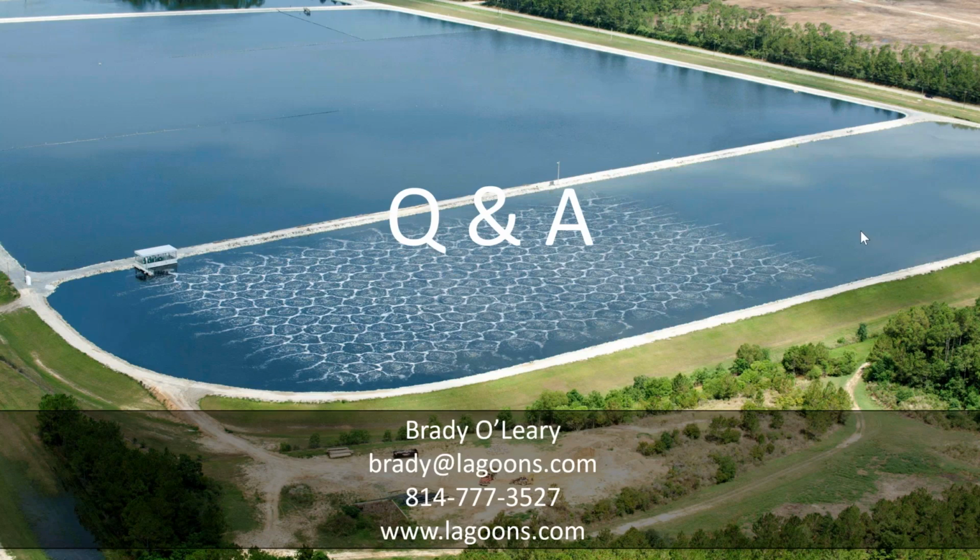Is installing fixed media in the lagoon going to improve the treatment capacity? Yeah, it will. It's usually important to make sure that the fixed media is aerated as well. Fixed media essentially becomes an attached growth site for bacteria. Bacteria will free float in your water column a lot of ways, especially the BOD ones, but you can grow more if you put stuff in there for them to grow on. You kind of hold them in place.